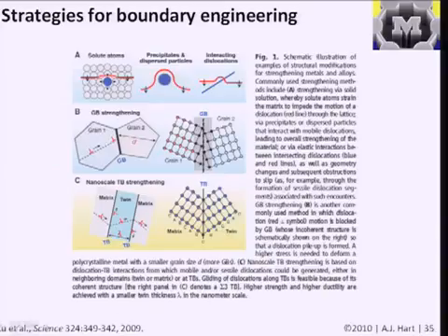And another one of the optional papers talks in general about strategies for engineering the boundaries of materials, engineering the grain boundaries. And there's this idea of cutting it up into individual grains, so you understand the deformation of the material by the motion between the individual pieces of it. And by controlling the types of boundaries, having their basic what are called regular grain boundaries, where you have essentially two pieces of lattice that are next to each other. And there are also what are called twin boundaries, where you don't formally have two separate pieces, but you have a boundary which is just a mirroring of the lattice, but you have one continuous piece. And what these researchers are talking about is their research and other research is saying that you can get different types of properties based on the types of boundaries that you engineer.